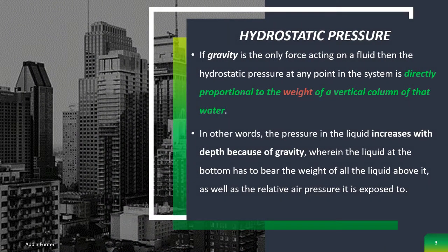If gravity is the only force acting on a fluid, then the hydrostatic pressure at any point in the system is directly proportional to the weight of a vertical column of that water. In other words, the pressure in the liquid increases with depth because of gravity, wherein the liquid at the bottom has to bear the weight of all the liquid above it, as well as the relative air pressure it is exposed to.